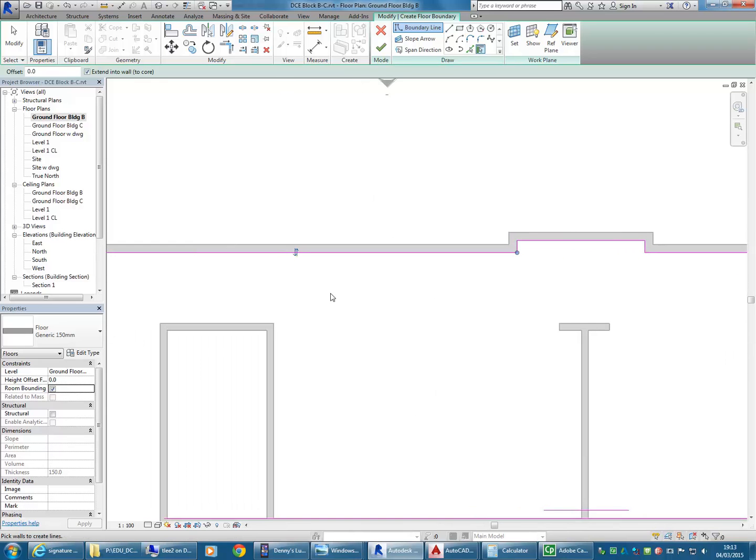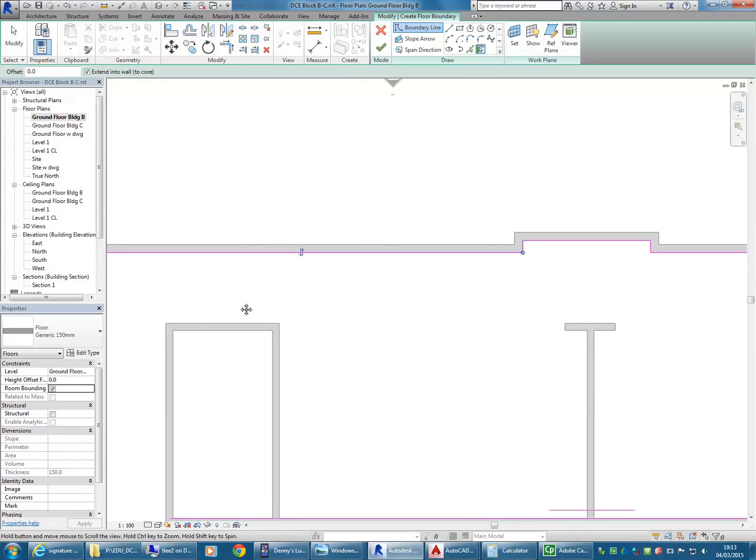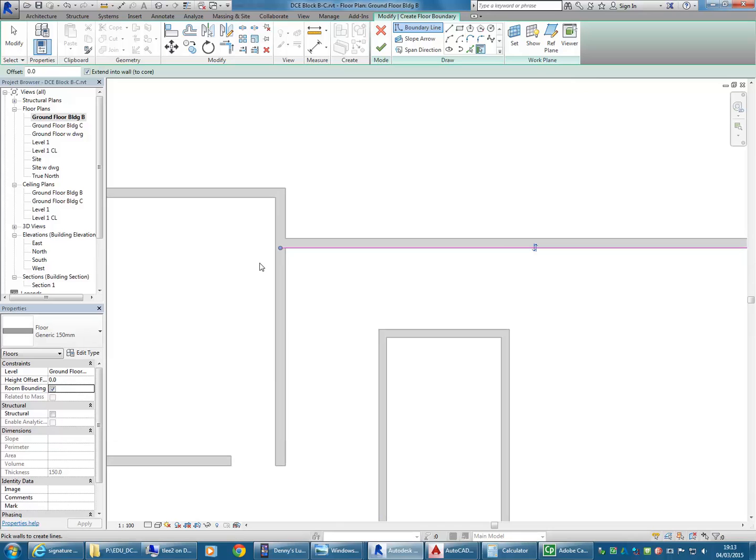But again, watch out if you have walls that are too complicated. If you're tempted to use the cavity brick wall, a double brick wall type, it might seem more accurate, but you're often going to create work for yourself because those walls have extra layers. They've got a layer of brickwork, then a cavity, and then another layer of brickwork, and one of those is set to be the structure, and the floor can detect that. That's what this option here will do.